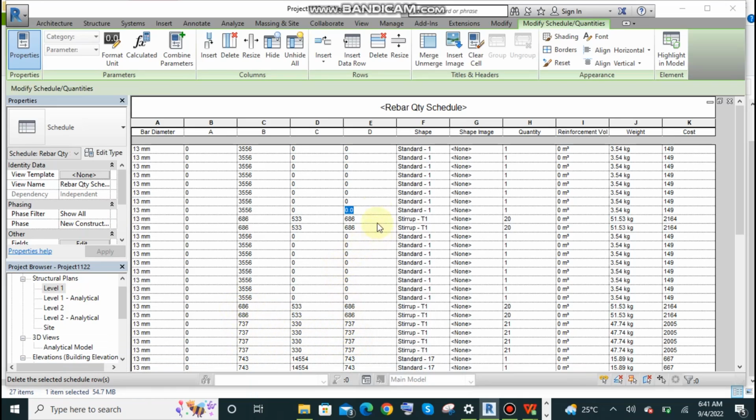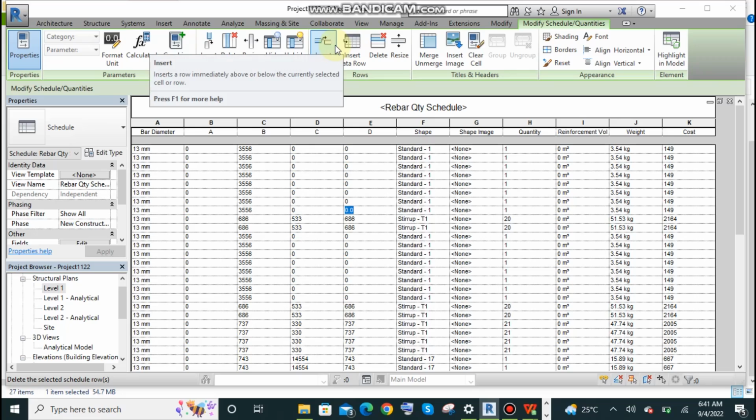Now here we have to calculate total required concrete for every individual member. So first of all, we have to calculate concrete for our columns, the total concrete required for our columns. After finding out the total concrete volume, we must calculate the number of bags required, number of trolleys of aggregate and sand, as well as the cost of those quantities. We must calculate that. So first of all, we have to find out the concrete volume for columns. So do the same procedure as well.